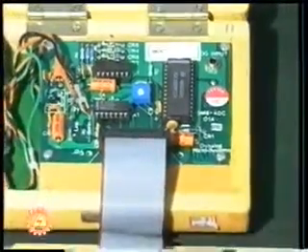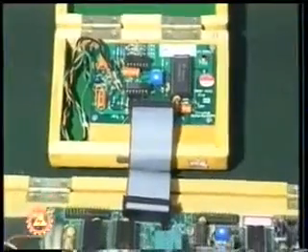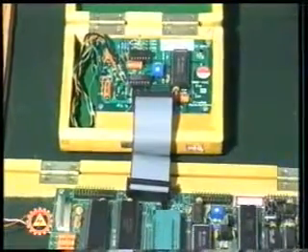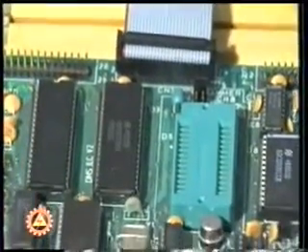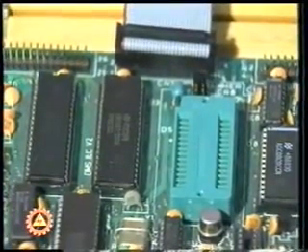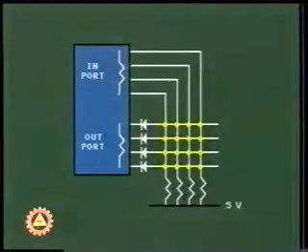Similarly, we may have the AD converter control signals polled by the microprocessor, or the AD converter can interrupt the processor when the data is ready. By interrupting the processor only when the data is ready, we are saving the microprocessor from keeping on polling the I/O device. So we are opting for a solution where a certain amount of software is saved.